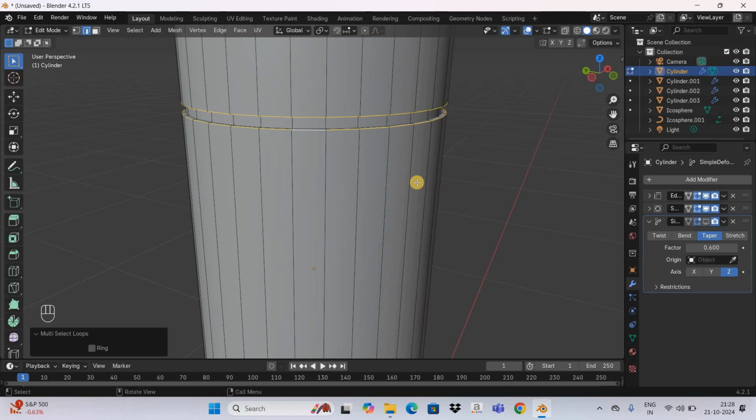So we are not going to add the bevel modifier in the edit mode. We directly have the bevel tool right here. And so you can select the bevel tool by clicking on this option, or you can directly press Ctrl B. And now you can enter the value directly, but I would like to simply press enter.